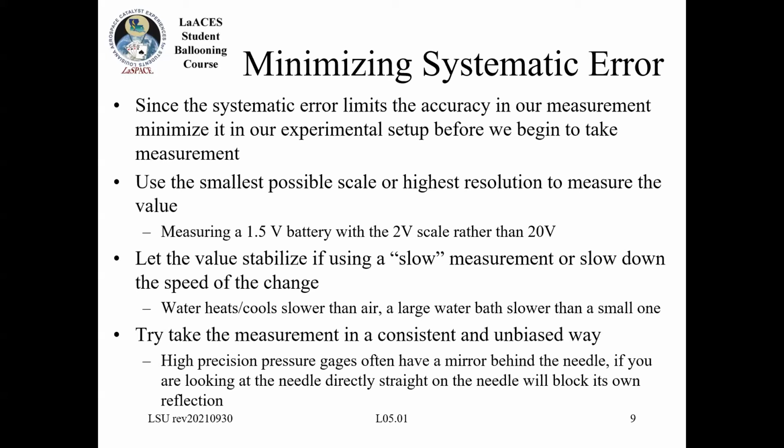And also you want to try and be consistent about the way you take your measurement. Or you can try and take mitigating steps so you're not shifting the scale by reading it a certain way. A really good example of this is if you're using a mechanical gauge, like a pressure gauge, you want real high precision, because that's basically a needle moving in front of a scale.